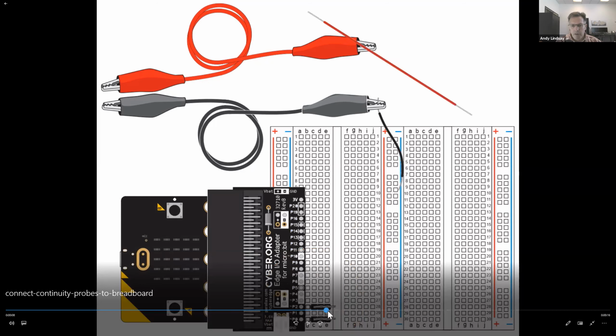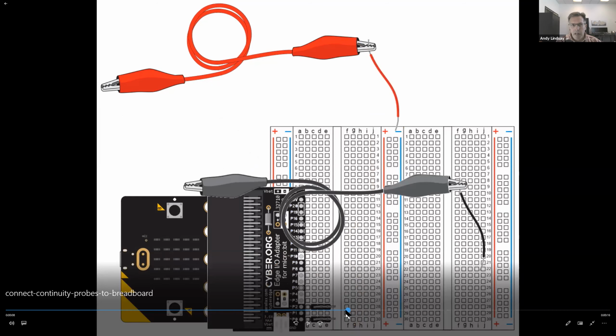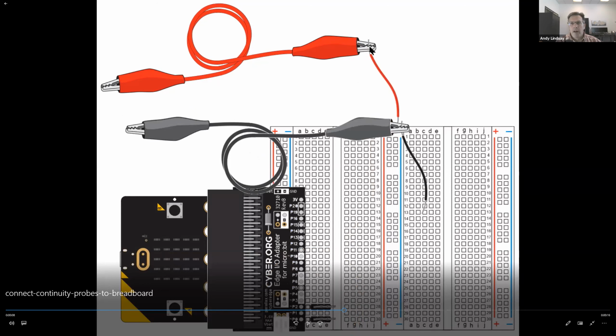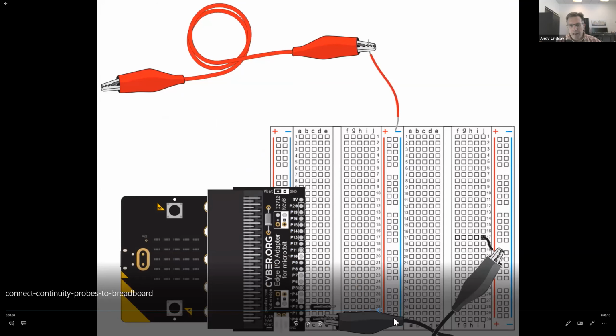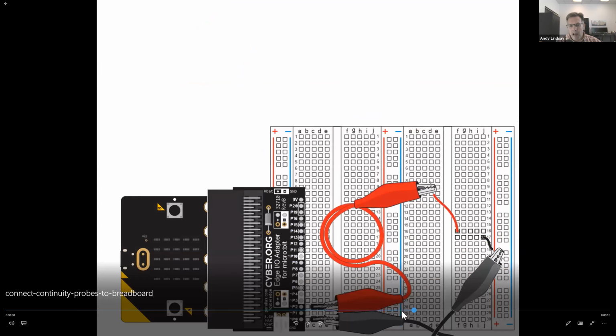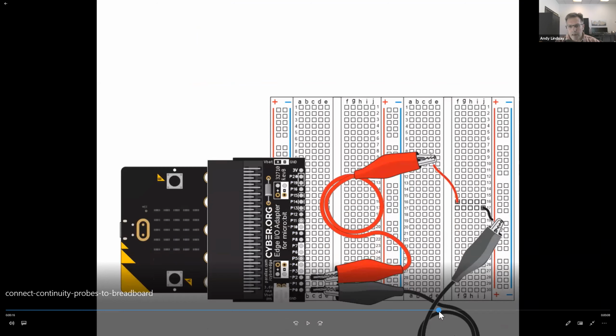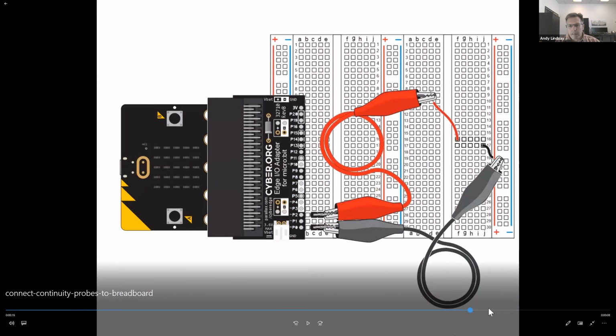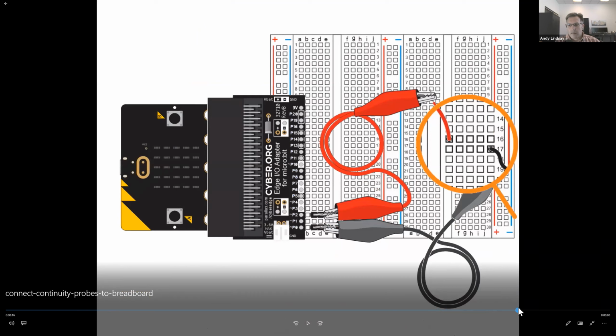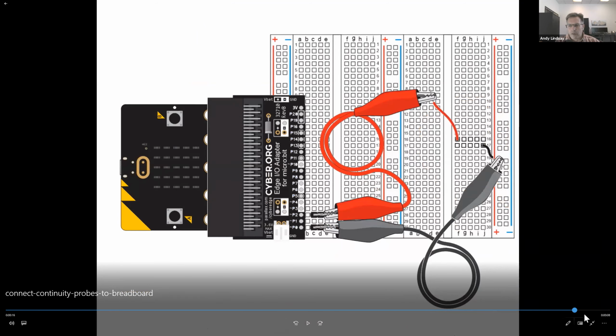And then after you've got those plugged in, we're going to have you grab the end of a red jumper wire with the end of an alligator clip and the end of a black jumper wire with the end of another alligator clip. And then the other end of the black alligator clip goes to the 3-pin header that's in on row 28. I'm going to move forward here a little bit.